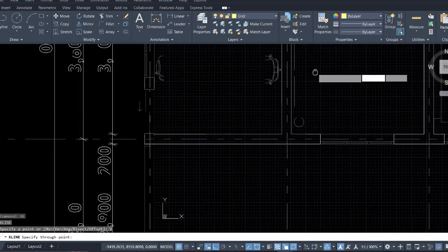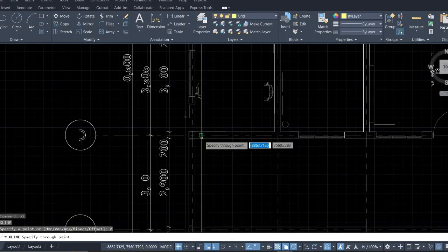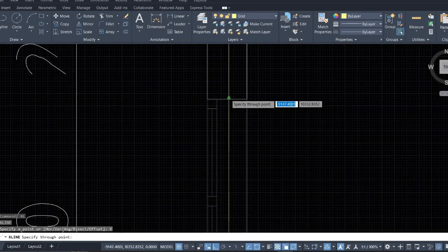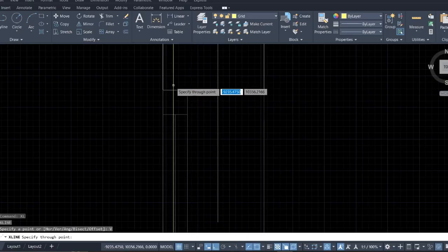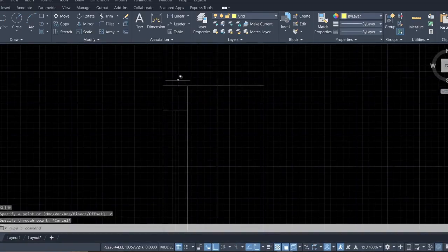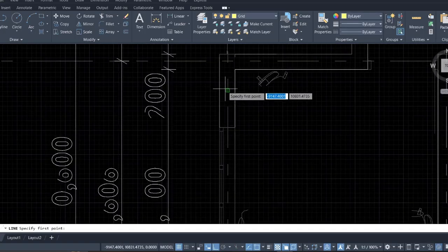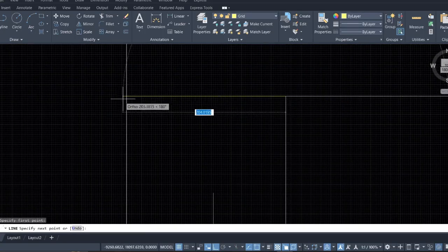And remember that you want to snap to the center of these walls. You want to bisect our walls, and it is not automatic that these architectural grids will have a center line. So to ensure that you create it at the center of the wall, you just come and create a line that can bisect this. Just come here, do a line.